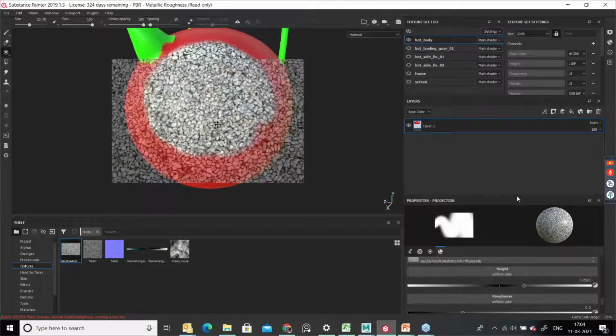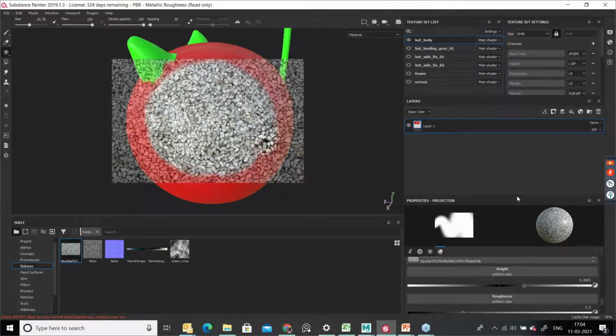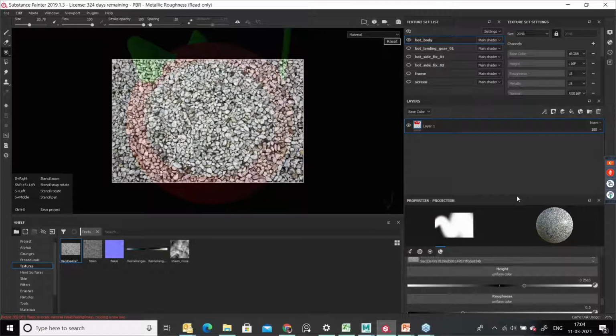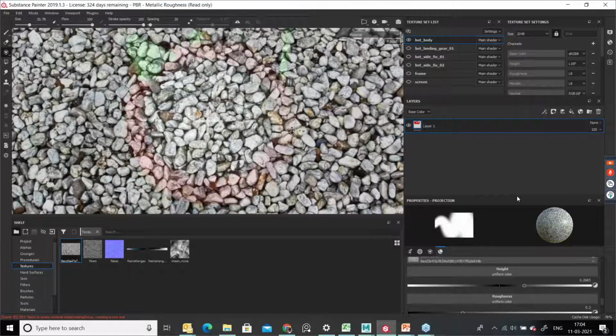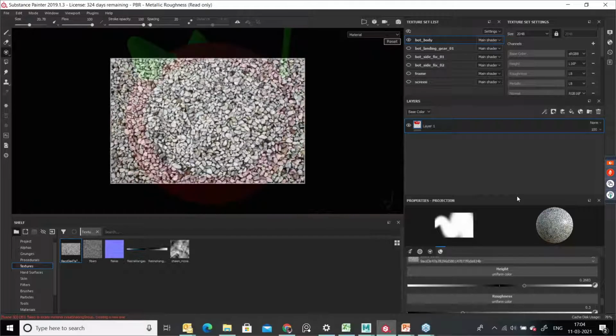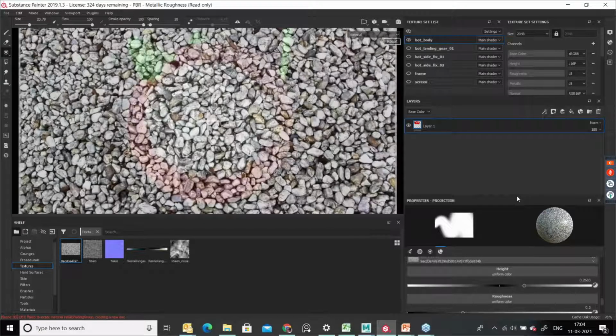Sometimes you may feel that it's looking like one single image. How can I apply it for the entire geometry? There is an option to scale this image. Press S and press the left mouse button and drag left to right to increase the image size.